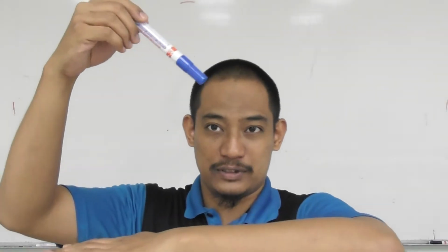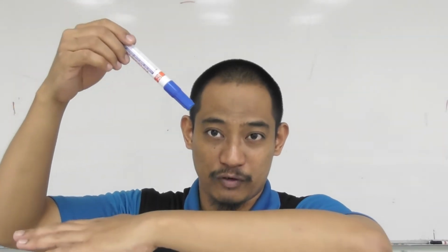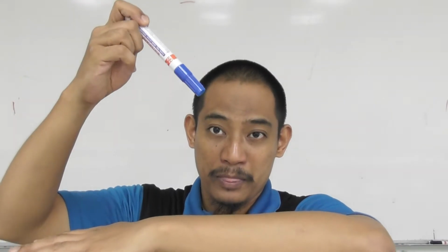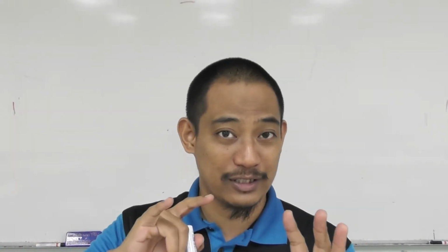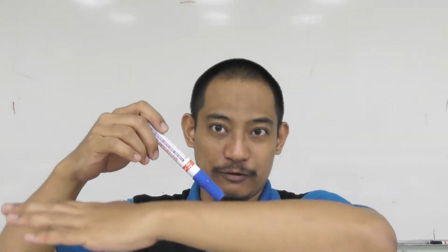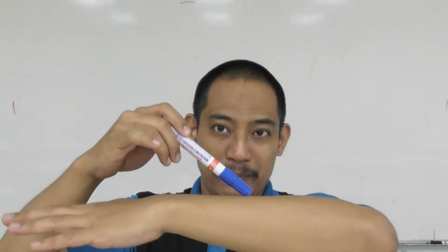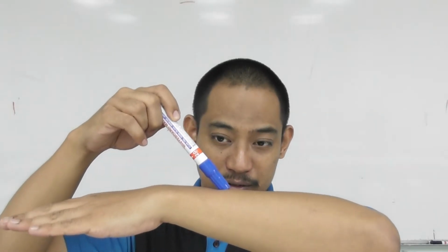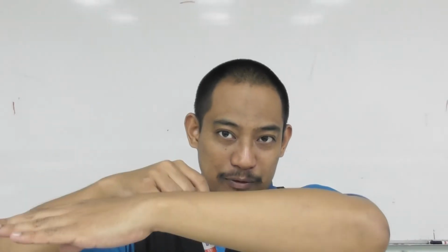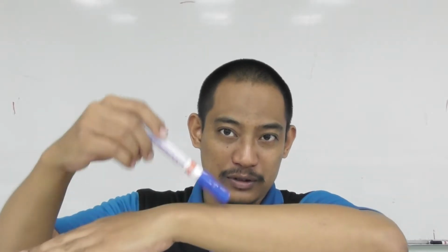So in that case, if this is the leg of a chair for example, then it is a member sitting on the ground. So the only restriction, because right now we haven't covered friction yet, but now assuming no friction, the only restriction is going down, right? It cannot go down.